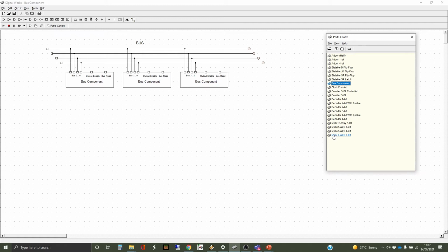It's called a bus because it comes from the concept of a bus in real life, where lots of people can get on and lots of people can get off. Actually, on this bus, you can only technically have one thing on at once. A bus is basically a set of wires, which is however many bits wide we want. We've got a 4-bit situation, so we're going to want to transfer 4-bit numbers. We might have, as I said, 8 components in our CPU, and we might want to connect from any one of them to any one of them, and that's a lot of different connections, as is fairly obvious.